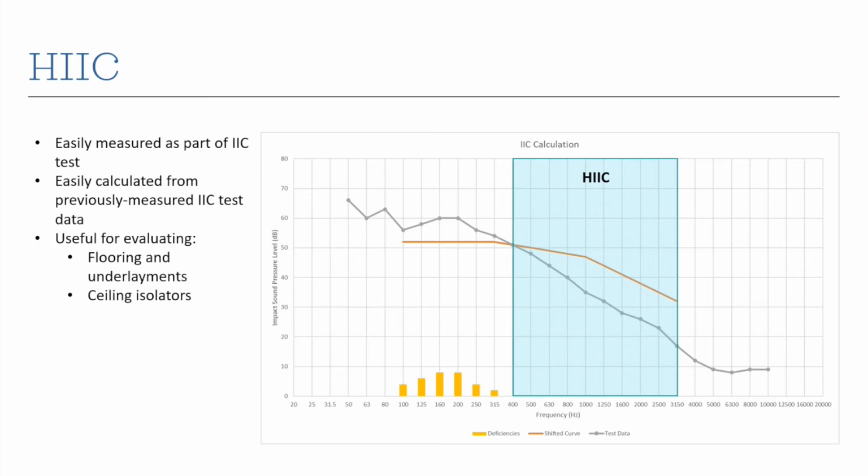And that can be particularly useful, say you've got an existing condo building where new people are moving in, or existing owners want to renovate their condos, they want to put in new flooring, right? So a lot of times the CC&Rs for those condos will have IIC requirements. The IIC depends a lot on the building structure itself.